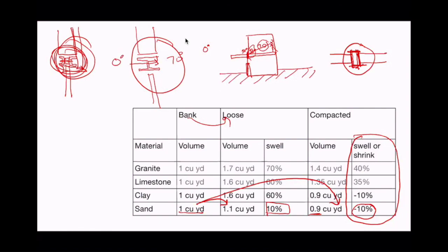Thermal bridging is all about heat, not moisture, right? Correct. Thermal bridging has nothing to do with moisture, only heat. That's where I got confused. Okay, but that said, moisture condenses when you have warm, humid air touching a cold surface that doesn't let moisture through it. If we think about where condensation happens,